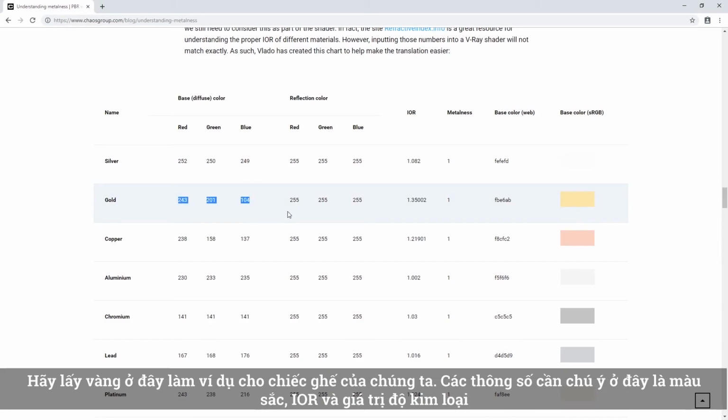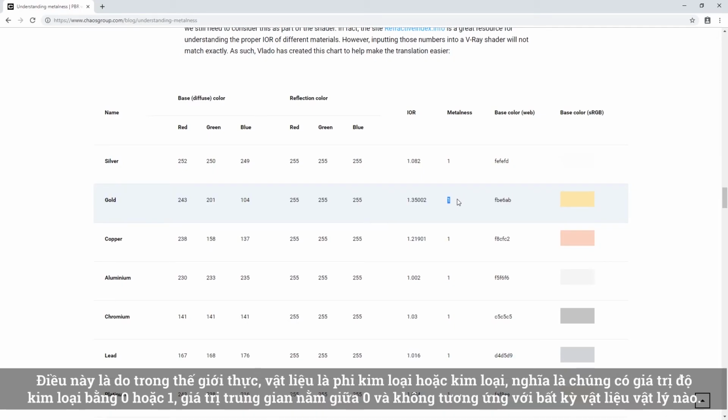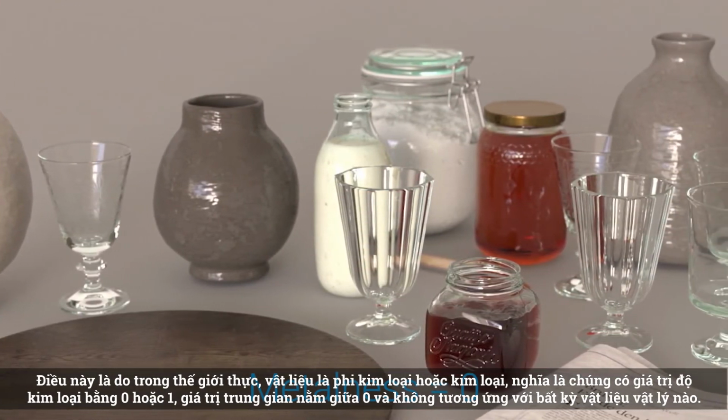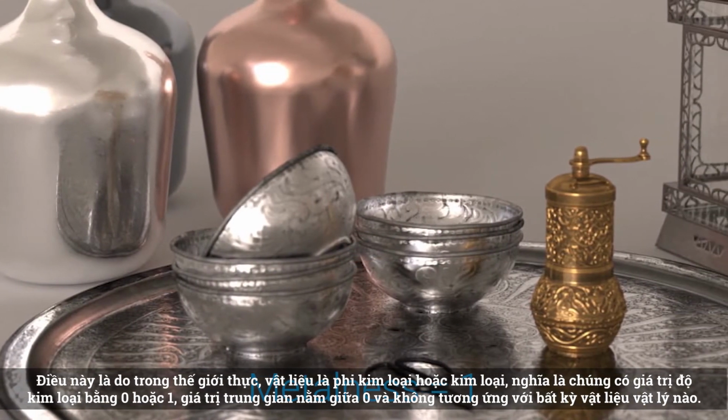The parameters to pay attention to here are the color, the IOR, and the metalness value. You'll likely notice that all of the metals here have a metalness value of 1. This is because in the real world, materials are either a non-metal or metal, meaning they have a metalness value of either a 0 or 1. Intermediate values between 0 and 1 do not correspond to any physical material.